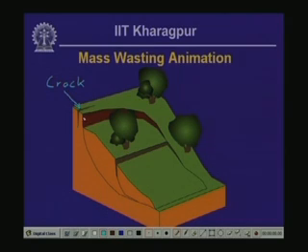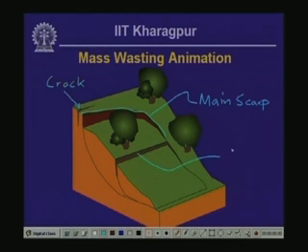and then what we saw is that a scarp actually opened up again near the top of the slope, from where the sliding mass actually came tumbling down. So this is called the main scarp. And then there were other scarps that developed in the process of slope failure.